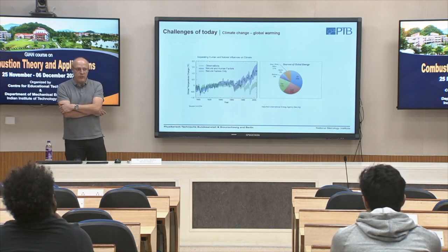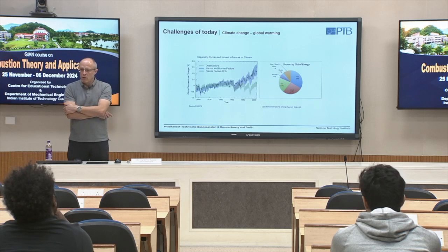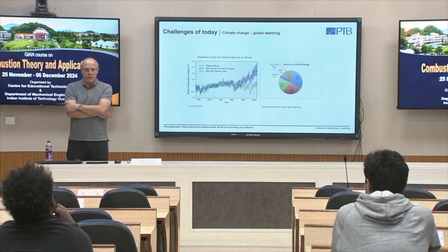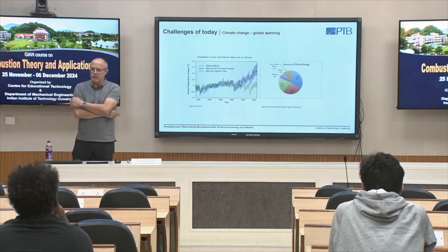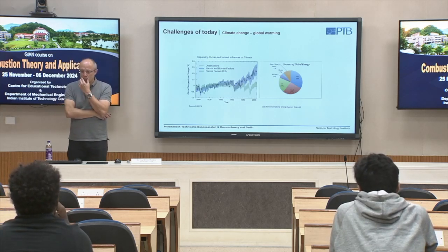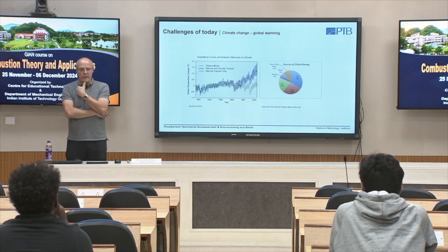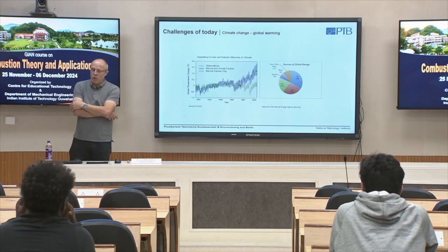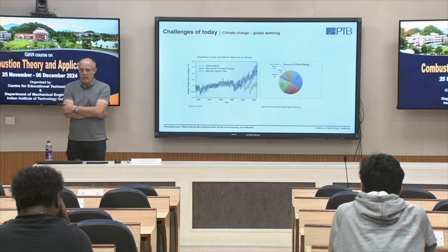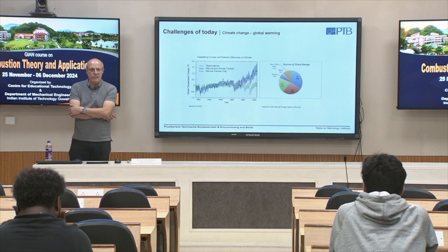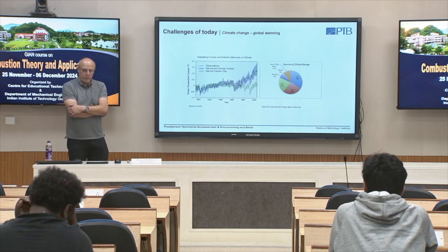As I said, we now know for the main combustibles how this ignition by an electrical discharge takes place and what the important processes are. For energies from 17 microjoule to 400 microjoule, we think we understand what is important here.